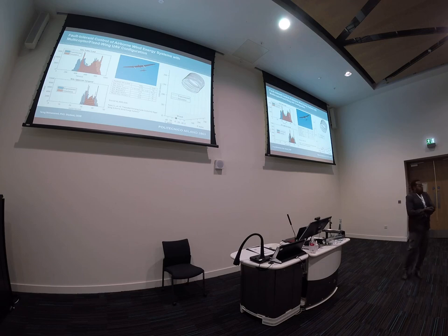In order to validate and verify the simulator, we take some experimental data. We find the path during looping, and we try to tune the controller in the simulator in order to follow the same trajectory. And when we get a path that is not the same, but more close, we try to collect the data. We take two main metrics: the airspeed of the kite and the tether load, the tether tension.